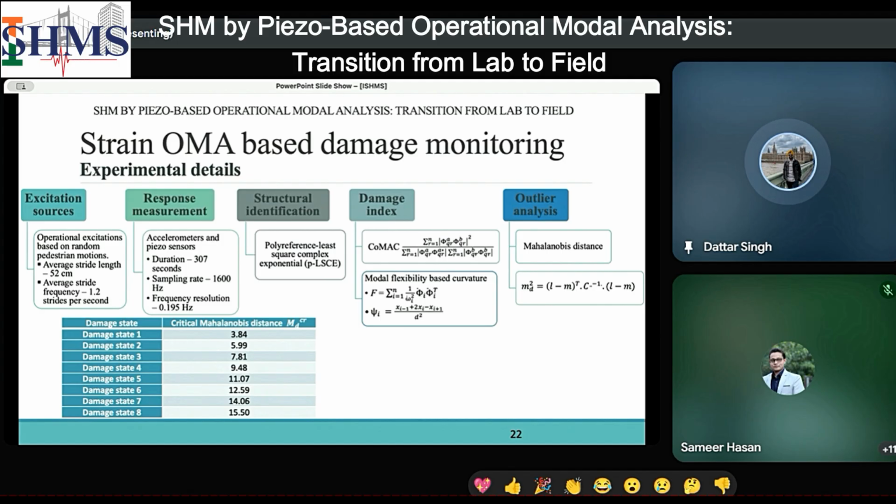It gives an overall indicator of how close 2 mode shapes are, but it does not cater to the variation at various measurement nodes. Let's say we have 10 measurement nodes to create a mode shape. It would give us a single parameter by comparing all the nodes. But in COMAC, we get a relative relation between 2 mode shapes at every node, and we can even choose how many mode shapes are to be considered to get that relative parameter.